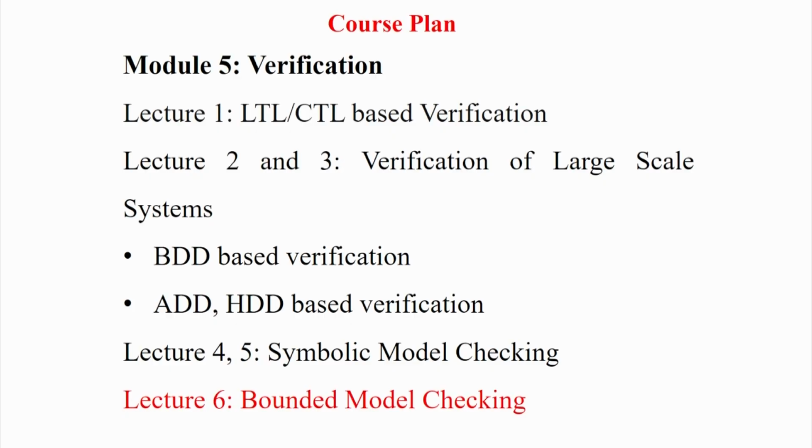But then we have seen that if you really want to go for NOC or SSE kind of structures, bit level modeling will not help you. So, there we had an entire lecture on high level decision diagrams, like arithmetic decision diagrams. But the problem there was that we do not have very good labeling and model checking algorithms on those high level decision diagrams. That is part of a research paradigm where people are trying to go for symbolic model checking not on BDDs, which are at binary level, but on the high level models. But still, as I discussed in that lecture, that is not very well matured.